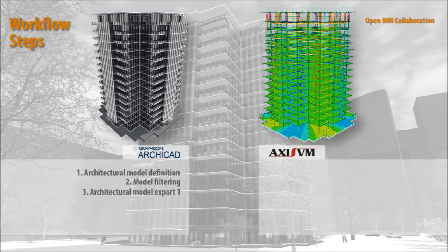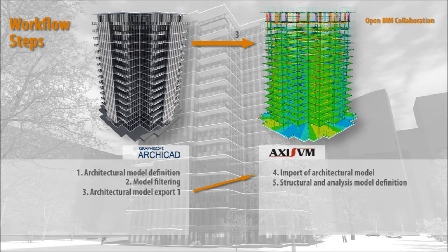The architectural model is exported in IFC format. Engineers receive the architectural model and open it. Engineers define the structural and the analysis model and its details based on the referenced architectural model. Engineers can query the initial profiles and materials defined by the architects. They add loads to the structure and run analysis and design calculations according to the required country standard and material